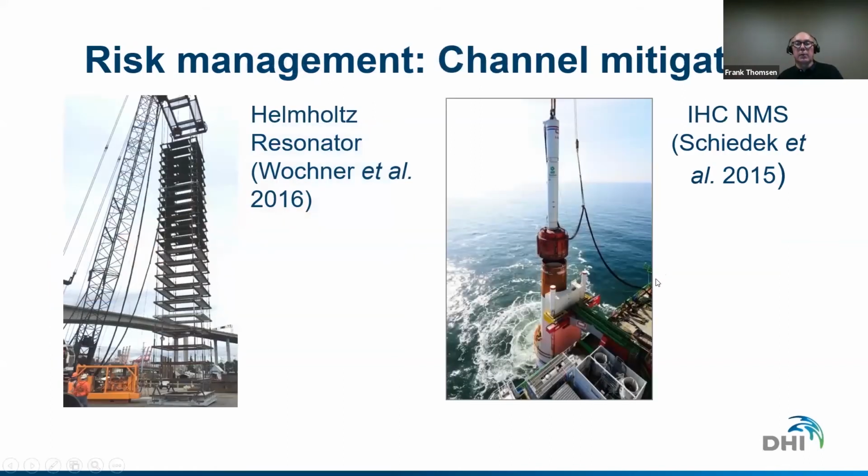Now, a second general principle is to put something air-filled in between the sound source and the marine life, where the sound gets trapped and reflected and the sound levels are reduced. And this is what we call channel mitigation. There are these Helmholtz resonators, like from the US. You can see a picture here, or this noise mitigation system that was developed in Europe and applied for offshore wind farm pile driving. And both these designs mitigate sounds quite efficiently under certain circumstances.